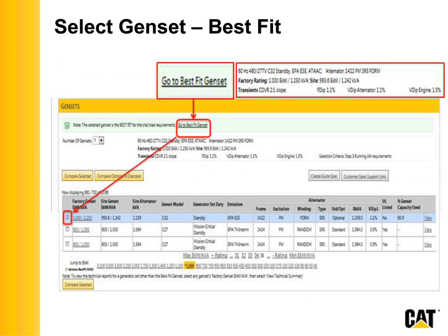All right, Stephen, we do have a question on this. How do you know what your Genset sizing is based upon? Okay, we talked about the different sizing parameters, your starting and your running and your harmonics. On your Select Genset page, there's a note called the Selection Criteria Note. It's in the top right-hand corner.